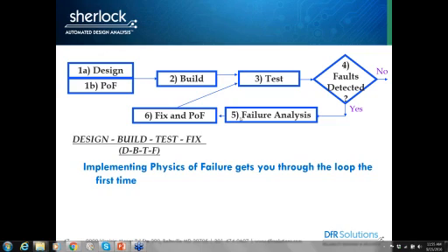For IPC TR-579, for thermal shock, theoretically copper is fairly insensitive to ramp rates. There's not a lot of temperature dependency in the thermal ranges that we're dealing with. If I was going up to 600 degrees C, there's something to be worried about. The only problem with thermal shock is really thermal gradients, and making sure I'm not getting some weird bending behavior because one side of the board is getting hot while the other side of the board is getting cold.